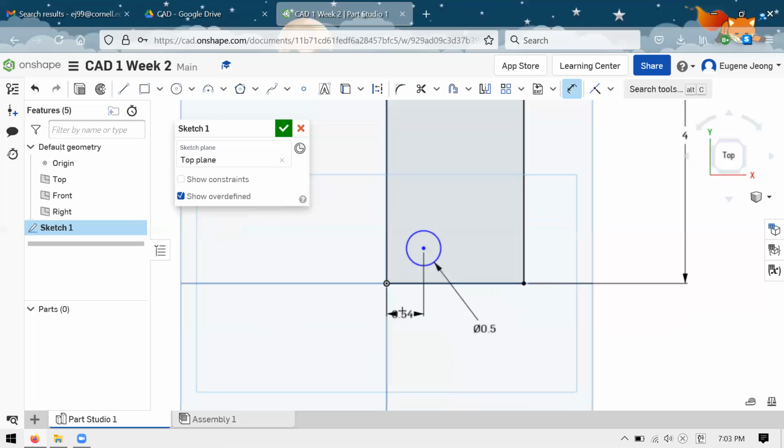If I put my cursor down here between them, it'll understand that I want to do the dimension horizontally. And you can see these guidelines reflect that because they're vertical. For here, I'd just be dimensioning the radial distance between them. This would be the vertical distance. Again, radial, horizontal, radial, vertical. So I want to do a horizontal distance, which I can do like that.